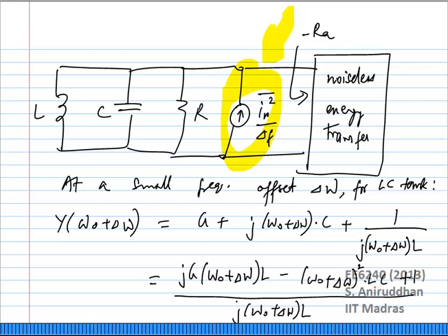The transistor switch and the periods will be exactly equal only at omega naught. If you move a little bit away, there will always be a residual resistive component, and therefore the actual frequency response of even the energy restored tank will have some resistance, some losses at other frequencies, and therefore it won't look like an ideal LC tank.